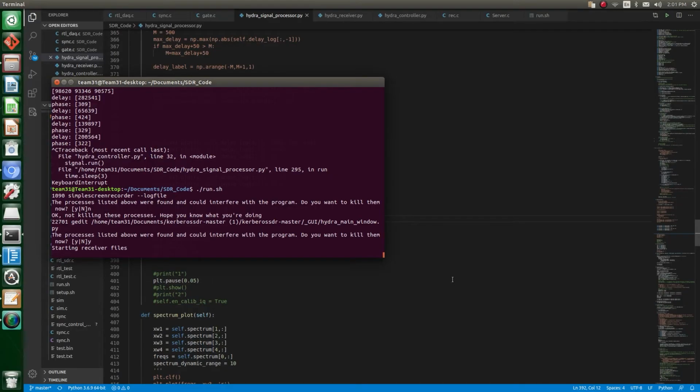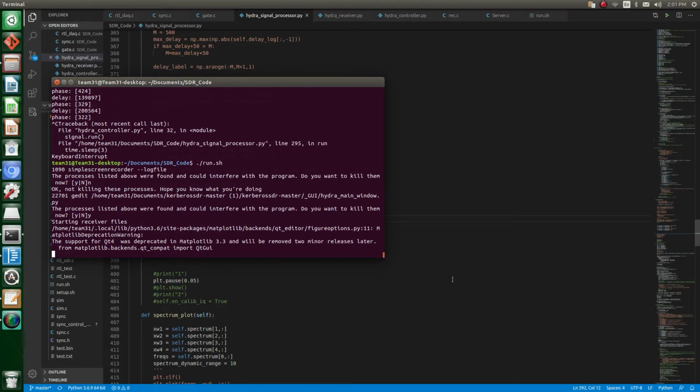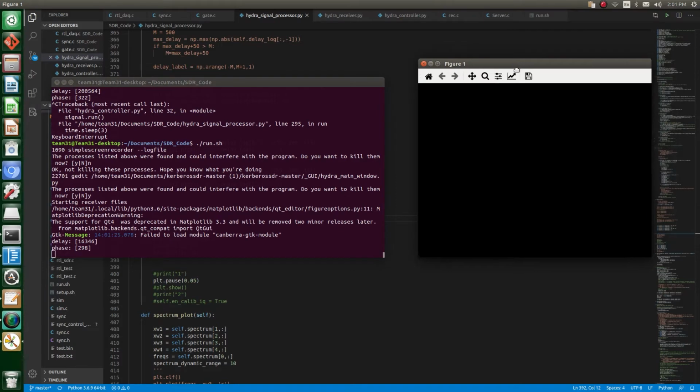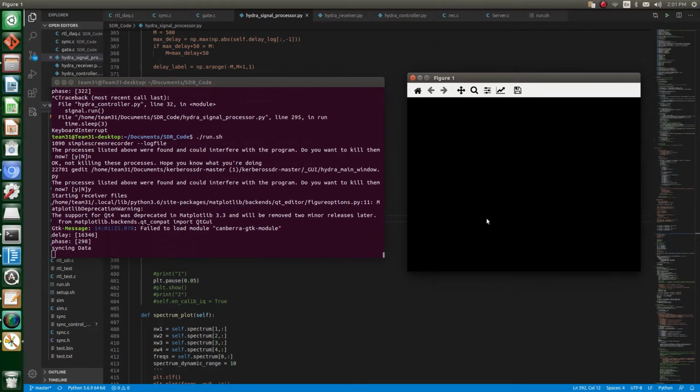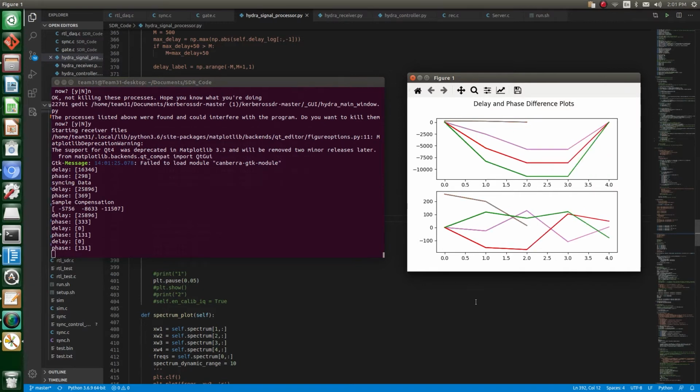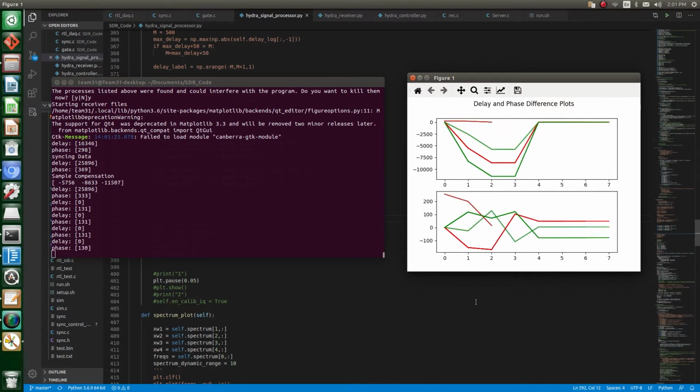Here is the initial setup of the software. The Kerberos SDR must be calibrated before use, and the parameters being synchronized are the sample delay timings as well as the signal phase synchronization. The sample delay must be set because there are 4 SDR units within the Kerberos, and they all power up at different times. Synchronizing their sample delay ensures a coherent unit.